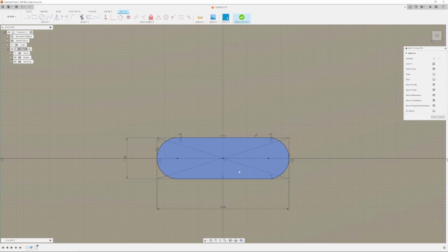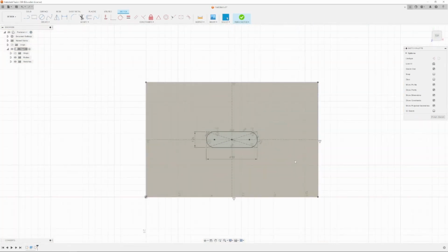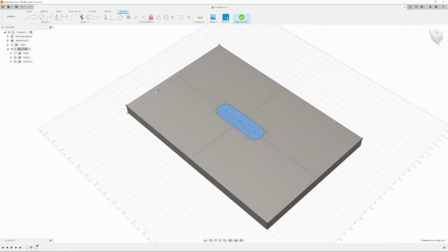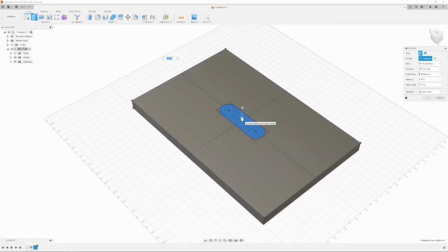So I have the stuff inside the oval, and I have the hole still is a hole, but that's in a different drawing, and so it won't show up blue. So I'm going to, instead of clicking Finish Sketch this time, I'm just going to hit E directly to jump into Extrude, which is back in the Solid Modeling tab, but it just takes me there automatically. And now I am here, and I have that shape to do. So I can just drag it downward, and I could select a certain amount of distance. I can type it in there.